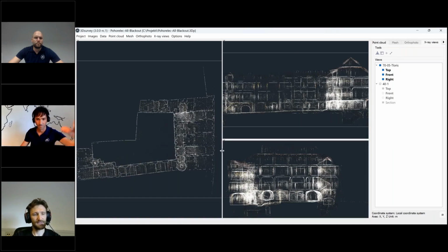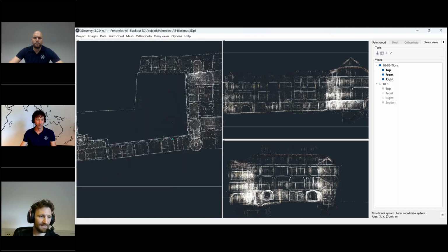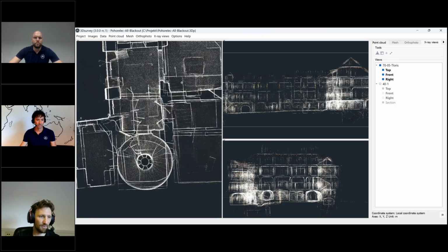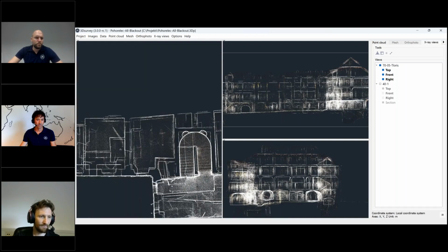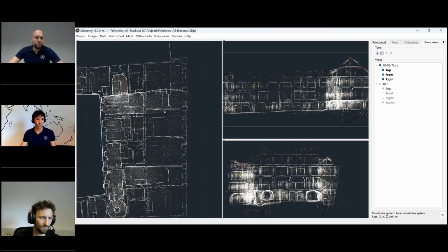I've used the default transparency of 70, and the resolution I cranked up to 0.5. So this is my top-down view. The X-ray functionality flattened all the points of this point cloud to this sort of plane. And it looks pretty impressive.